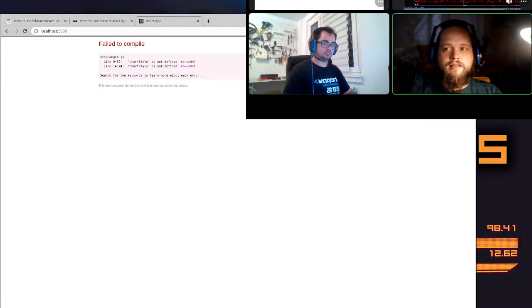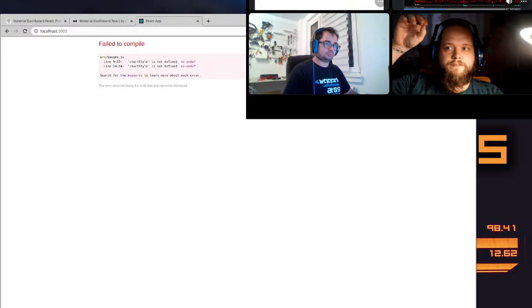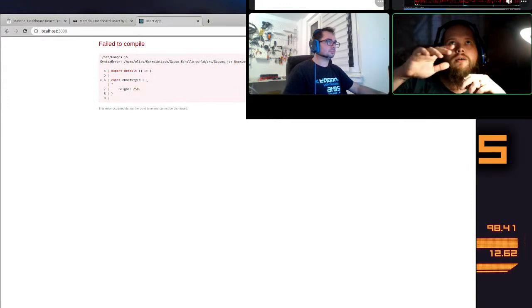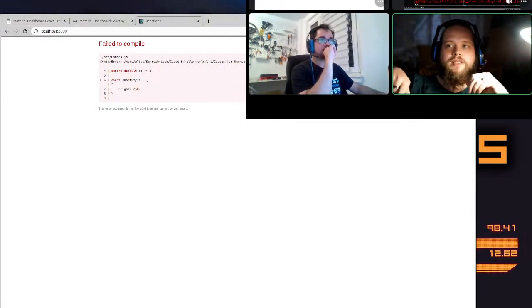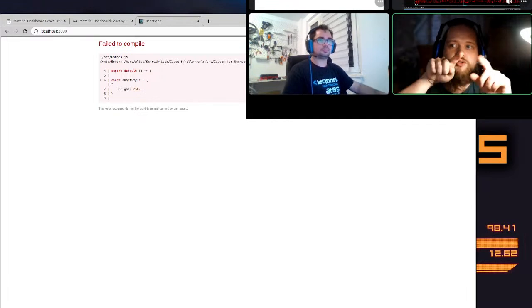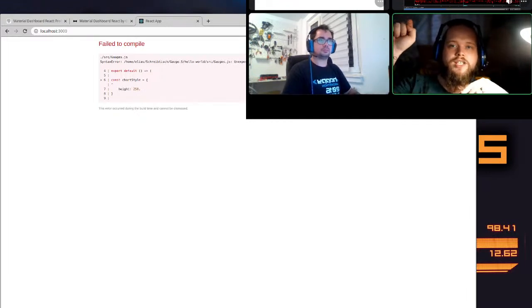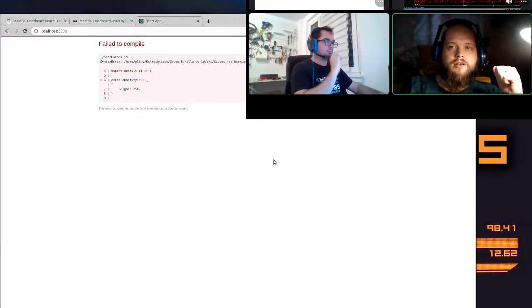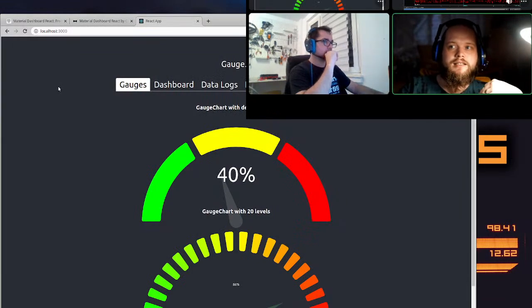And then on the right-hand side there should be a menu where the user can choose which parameters to display on the gauges. So there will be a small menu with all the parameters that are currently sent from the ECU. Then you can choose which parameters you want to display, move those gauges, and save this as a template for the display. So you have this template, and you can load it each time you start, and this will be displayed.